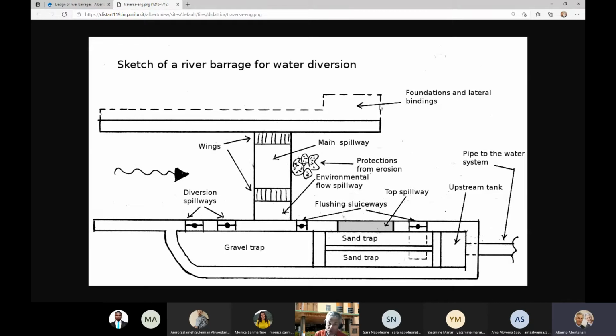So the solution is top discharge. There is a top weir, so that in case this happens, like in nature, in case an extreme flood comes, you can predict what's going to happen as a reaction of the infrastructure. And the reaction of the infrastructure is that the excess flow goes in a controlled way over a weir and goes back to the river, which is fine.